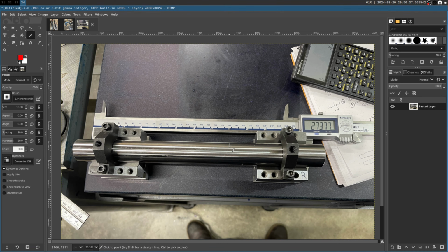So this is the little dumbbell that I built. Effectively, I treat this as a parallel, where the top part of the bar is parallel to the bottom part of these flat surfaces, and these flat surfaces are in the same plane as each other because I set this whole thing up on the surface plate, right?